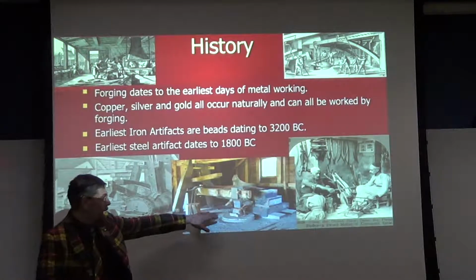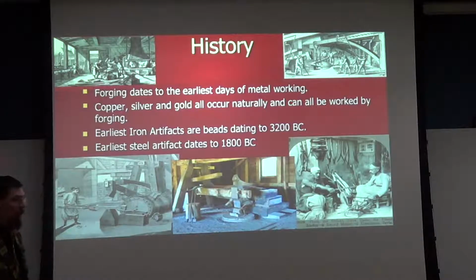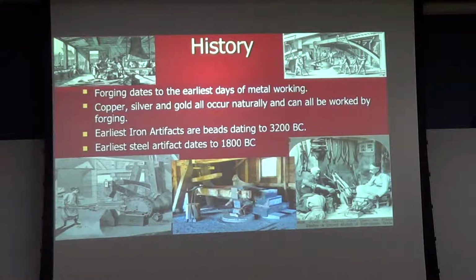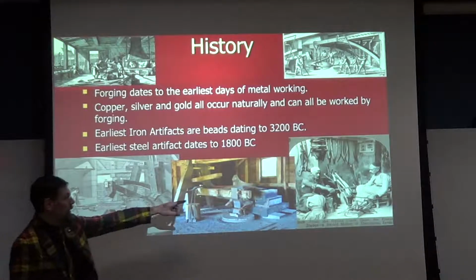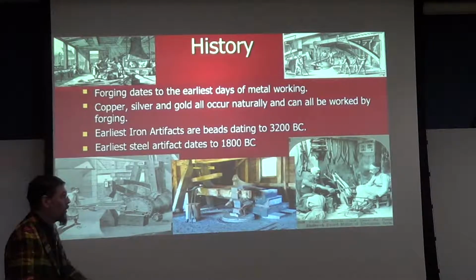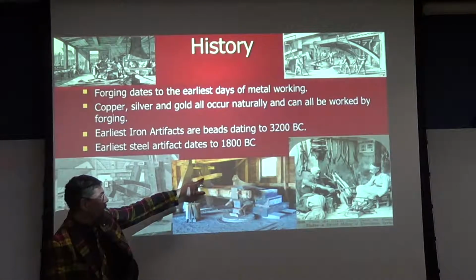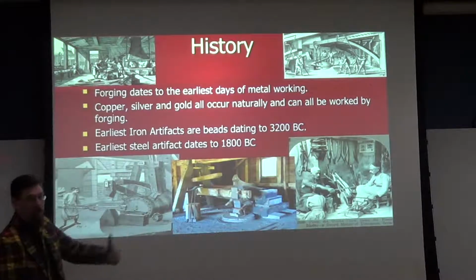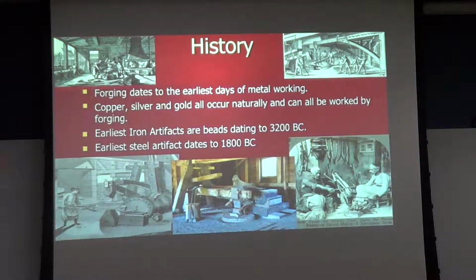This is an older hammer that's been restored and is available for viewing in a historical village kind of situation. Those hammers were powered by water. You'd have a large shaft outside the building with a water wheel on it. They would turn this cog, which would in turn lift this, and this would just drop under the action of gravity. Or sometimes they would do what they've done here, put a big timber above it, which acted like a spring to force that hammer down more rapidly. And that kind of technology was used for hundreds and hundreds of years very effectively.